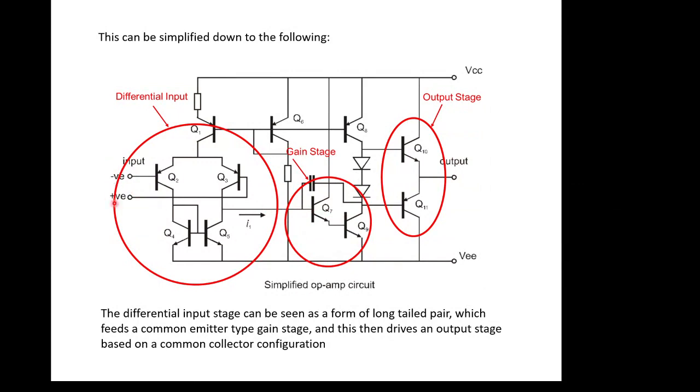So we've got a differential input, so a plus minus input coming in. The difference between these two inputs is turned into what's called a single-ended output. So this is the only output, and it's referenced to this supply here, which is never moving. That is then amplified hugely, and then it goes into this buffer stage, which is called a push-pull stage, to allow us to actually get some current out of this device.